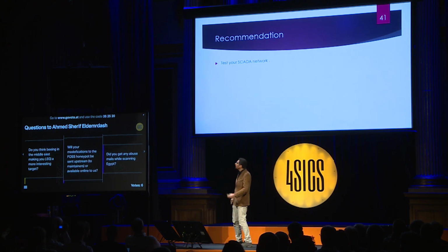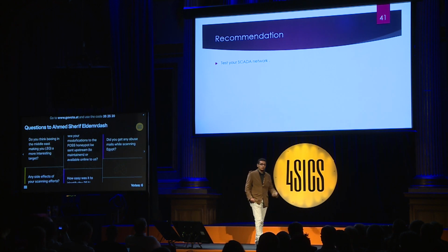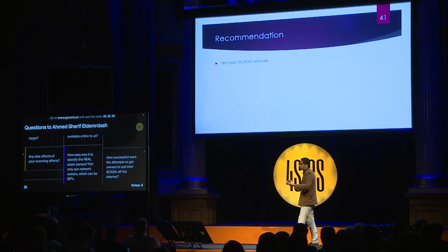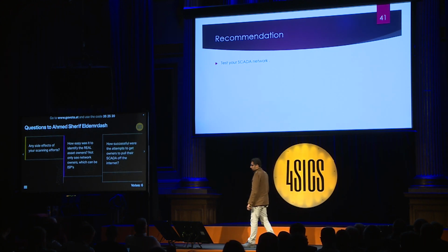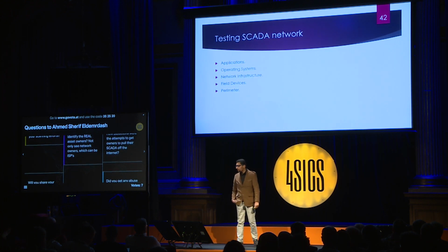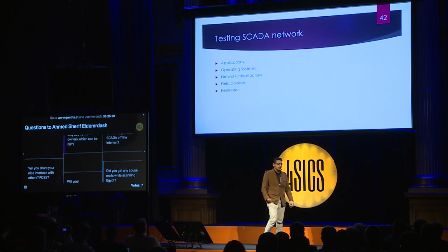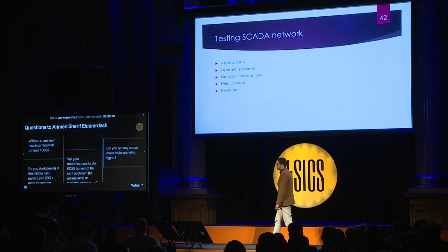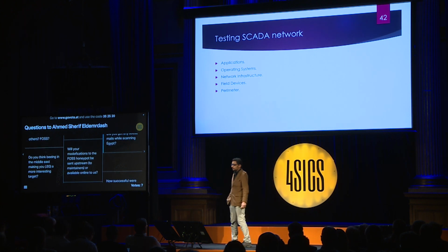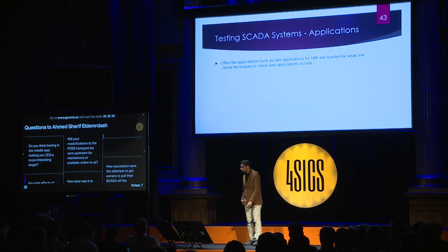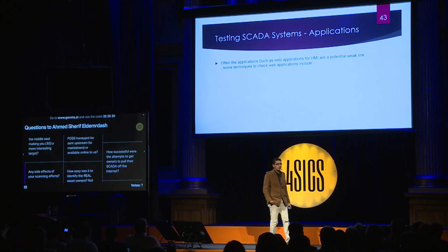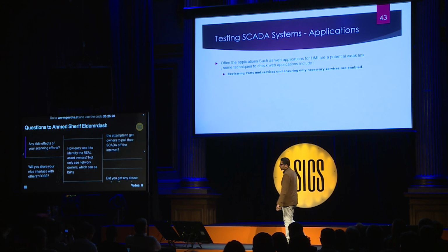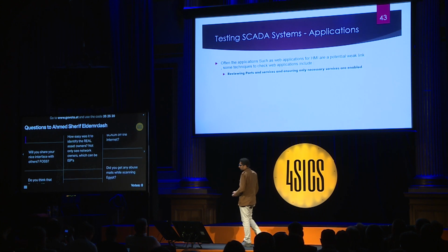So, what's my recommendation for you, or what you can do on your systems? I think testing your SCADA systems is a good recommendation. So how can you test it? It's really simple. You can test on a lot of levels: application level, operating system level, network infrastructure, field devices, perimeter. On the level of application, there are a lot of web applications for HMIs which have a lot of weak points. So you can review your ports and services and ensure